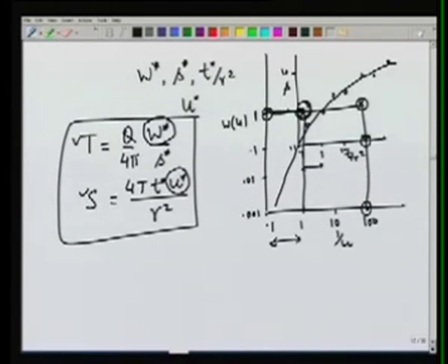So we have seen some methods of estimating the parameters S and T. For example, Jacob's method, which required data for a very long time. Then we have Theis type curve, which can use all the data set and compute the values of S and T. We have also discussed all these methods only for confined aquifers. Unconfined aquifers are a little more complicated because the thickness is not constant, it depends on the head H, and we will have to make some simplifying assumptions to obtain the equation of motion. That we will do in the next lecture.